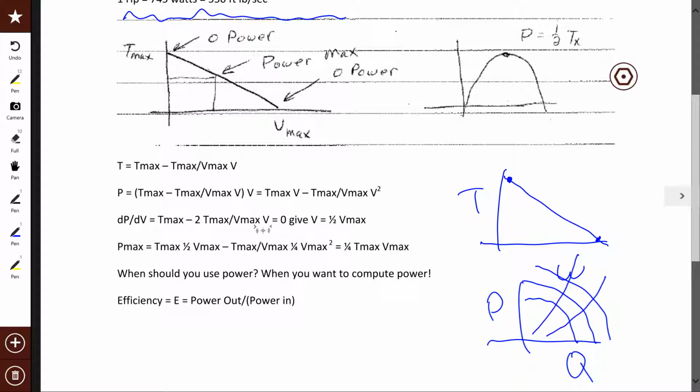The reason that you have multiple curves is they'll say, okay, this inner curve corresponds to using a pipe size of maybe a 1/2 inch diameter pipe, and the other curve might be for a 3/4 inch diameter, because they don't know what pipe you're going to hook up to their pump, right? So they make these measurements. And in a case like that where they're curved, it's not always in the middle.